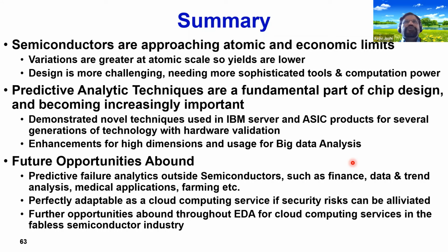Well, as you know, when you go down, the roadmap is nanosheet, and then there are stacked devices. So what is the interaction between the neighboring devices from the stacking point of view? Will there be an issue? As far as the parametric side, these parameters will still remain the same. I don't see any newer thing in there. You have all these VT, L, W, mobility, these are the basic physics. But other than that, if there are neighboring effects or stress effects, those kinds of things can be an issue or possibility.